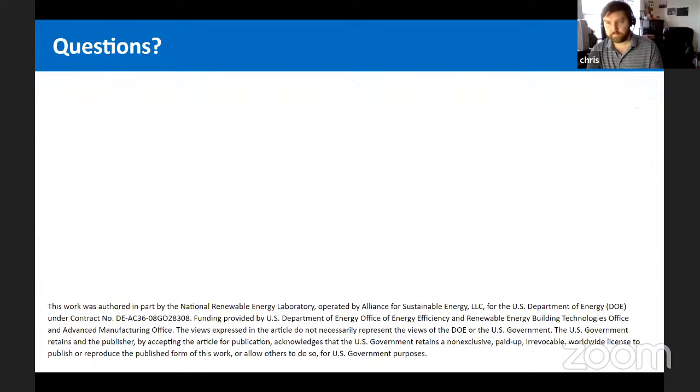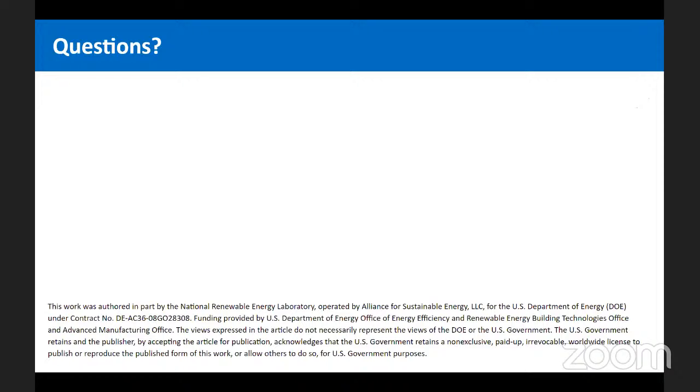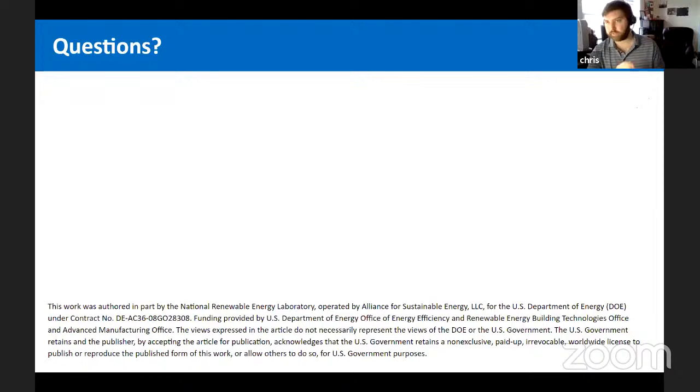Topography can change. Chris, do you want to talk about that one? Sure, yeah. I mean, that's perfectly acceptable to have buildings at different elevations. At the end of the day, everything gets converted to that 3D format, so those differences in elevation will make it into the urban model. Because we use the GeoJSON, which is a 2D format, and a lot of the examples I showed were flat ground, that's not a limitation. You can model any different elevation changes between those building massings or footprints.